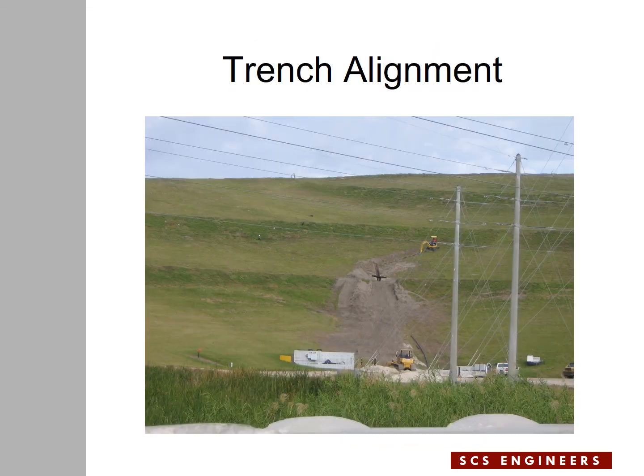Here you see the alignment. On the lower part of the slope, the trench is already backfilled. You see the surface of the dirt backfill in the trench, but somewhere up there, when a roll of the geotextile is placed across the width of the trench, it changes angle because of the center line of the concave surface.